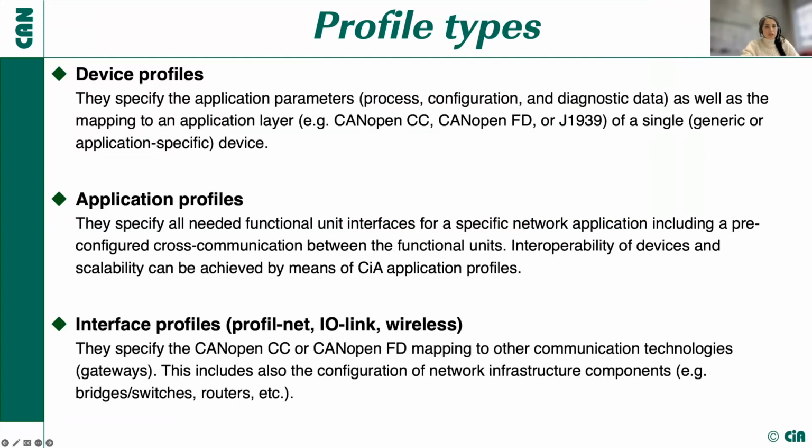In this slide, I would like to talk more about the profile types. As I said, we have device profiles that specify the application parameters as well as the mapping to an application layer, such as CANopen Classic or CANopen CC and CANopen FD or J1939, of a single device, either generic or application specific.